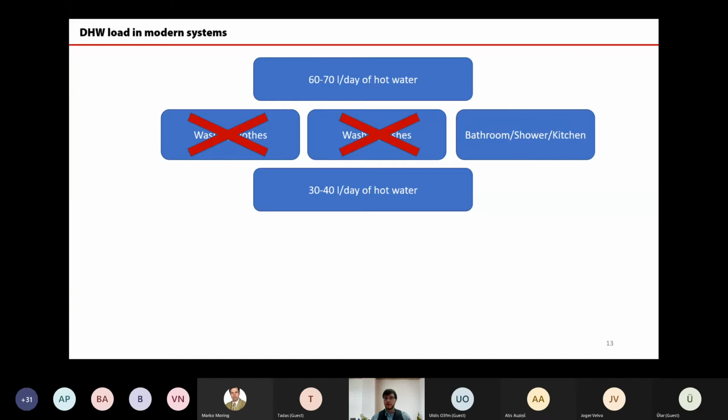And that's really, you can say, a trap which can be easily seen in designing of the systems, because if I have calculated capacity with safety and I have selected the valve for this capacity, and on top of this my heat exchanger is having surface margin, all these safety margins multiply and lead to basically very bad control of the system in winter specifically. And winter mode is very, very crucial for the brazed plate heat exchanger. I will tell you in a couple of slides why.